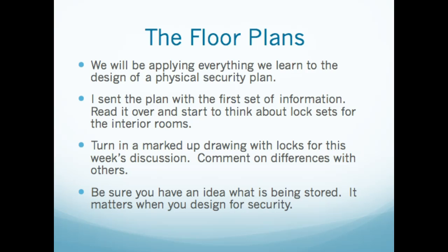You're going to turn in your marked up drawings per the discussion, then you're going to comment on differences that you have with others, because no two drawings are probably going to be exactly alike. Someone's going to put a particular type of lock on. I know which room it's going to be, that everybody's going to have a different type of lock on. And then I want you to discuss why you decided to put the type that you put on a particular room when someone questions it. Why did you put an office lock on this room when I put a passage set?